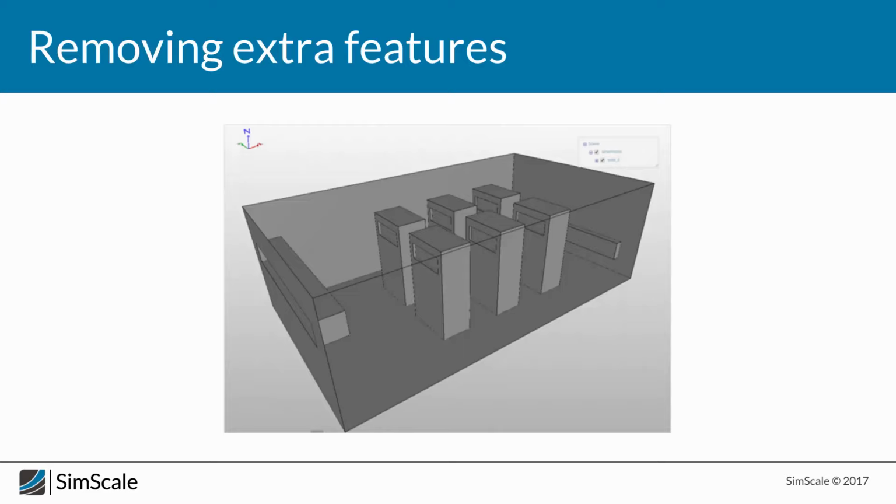The second thing when it comes to cleaning up the process is that even if we have those little features and we try to resolve the mesh in order to represent them, this will increase the size of the mesh itself. What it means is that we get a better precision of the solution around the door handle. Do we really need a good resolution of the mesh near a door handle? I don't think so. We'll be more interested in a good representation of the flow next to an inflow, next to the chamber itself, next to the reagents and parts where we have the inlets, the outlets, the reaction elements. That is the focus, not the little elements, knobs and small things. We should simply clean them up.